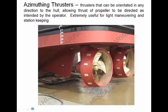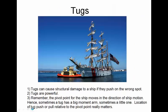Some vessels have what are called azimuthing thrusters. Now these are basically propeller drive systems that have the drive shaft come in, come down, and then mate right here with this propeller. This gives the ability for this device to circulate 360 degrees. Increases maneuverability. You can point the thrust. You can direct it exactly where you want it. Super, super effective for maneuverability. And we typically will call these guys a Z drive because this little driveline shaft that I drew looks a little like a Z. So that's a Z drive.